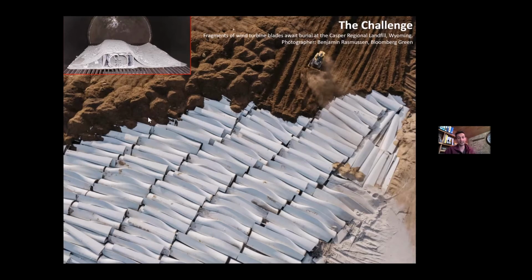Thermoplastics are becoming more and more possible, and this is particularly the case with smaller wind turbine blades, because then you can recycle the composite material a bit more readily in comparison to thermoset-based composites. Incineration may also be an option, particularly if the fibers are not inorganic, like glass-based. It's just more economically viable to either landfill them or to mechanically degrade them and then use them as fillers in concrete, for instance.